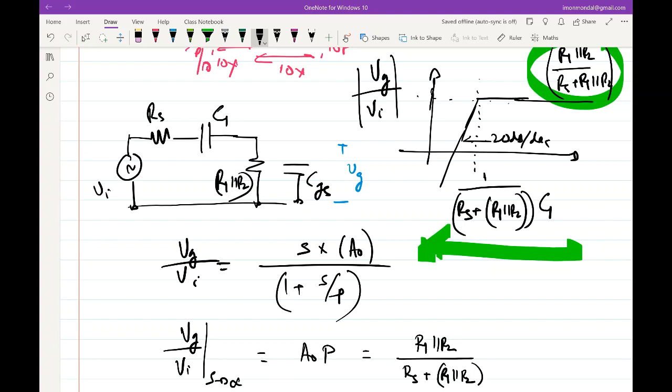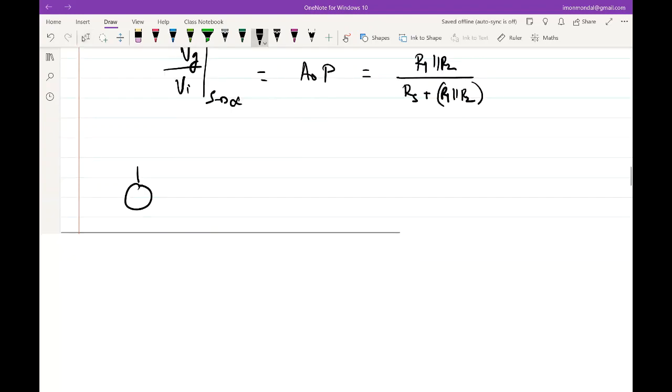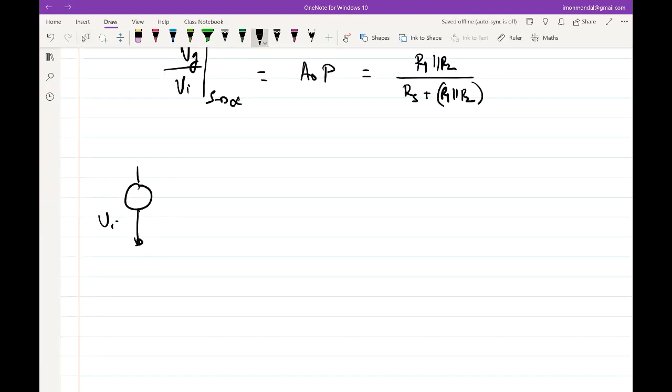Okay. So this is the expected high pass response if CGS were 0. But now let's assume the other condition, that at relatively high frequencies C1 is supposed to act as a short circuit, right? Ultimately, the whole goal of putting C1 was to block the DC and pass everything else. So let's assume we have designed it such that C1 only blocks DC and passes everything else, which means at non-DC frequencies, or signal frequencies, however you might want to characterize this, instead of C1, I'll have a short circuit. Then I'll have R1 parallel R2.